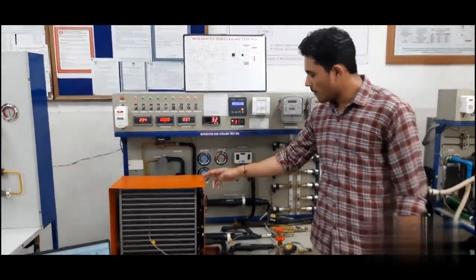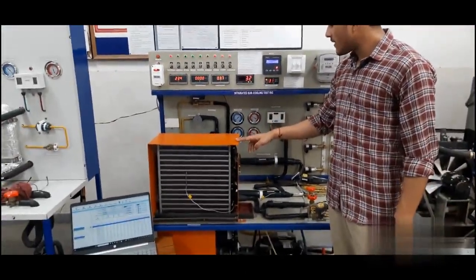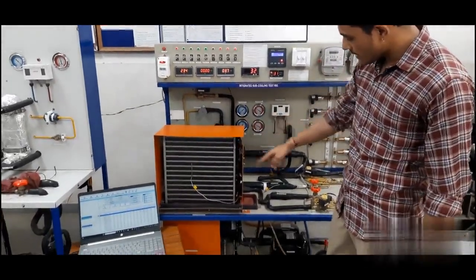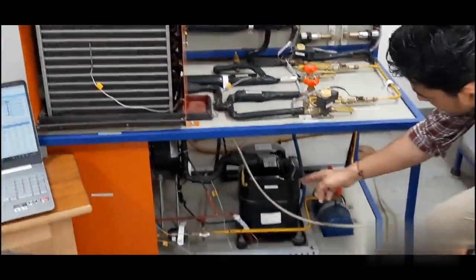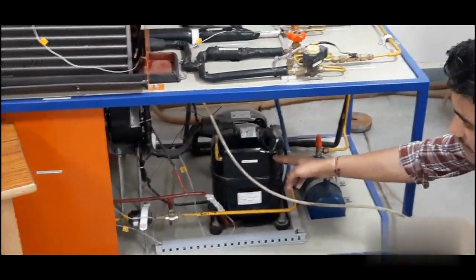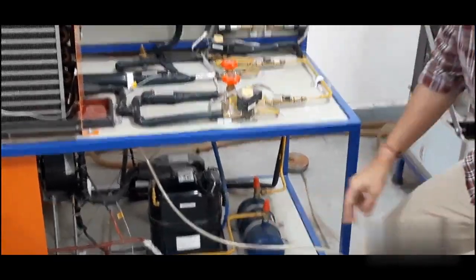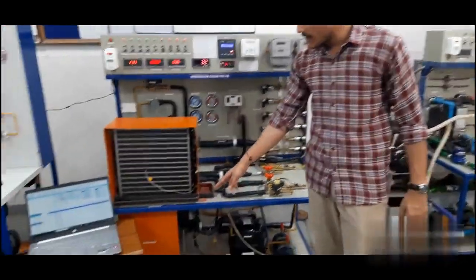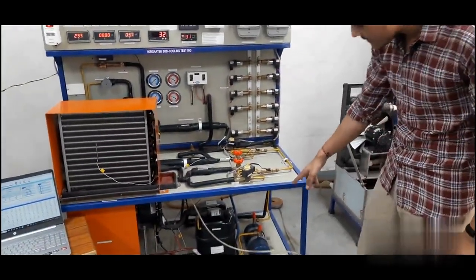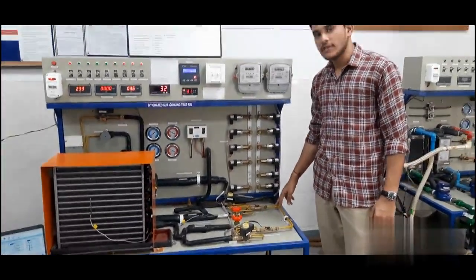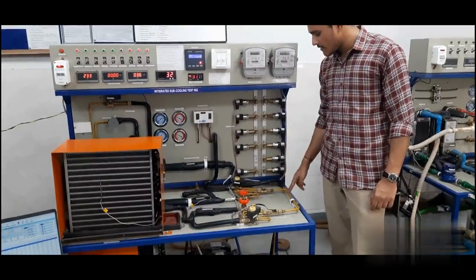This is an air-cooled evaporator. It changes the phase when a saturated liquid refrigerant enters into it. Then the saturated vapor enters into the 1 ton compressor. The compressor helps to increase the pressure of our refrigerant. Then the superheated vapor enters into the air-cooled condenser. After the condensing process, all the refrigerant enters into the receiver. After the receiver, the refrigerant is divided into 2 cycles: one goes into the main cycle, the other into the subcooler cycle.